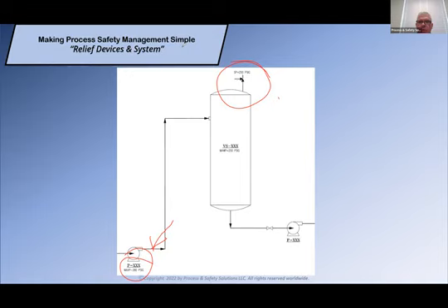So that is why it's so important that we document all of our scenarios and how that relief valve was sized. That way, if I ever want to make changes to this system in the future, I can go look at that process safety information and determine whether I need to relook at resizing that valve, or whether the scenario is such that I can go to 280 and it's fine. So that's another scenario. Let me clear this.